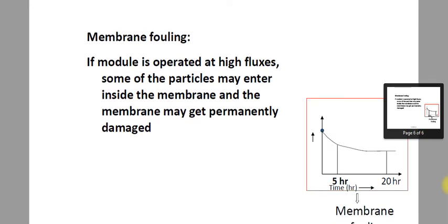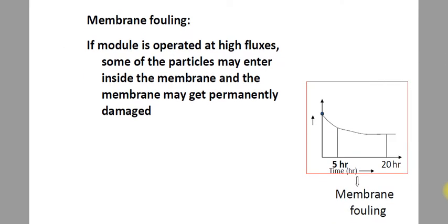Now there is one more technical factor which affects ultrafiltration, that is called membrane fouling. So what is membrane fouling? It is different from concentration polarization or gel formation. Because here you are separating out solid particles, there are chances that solid particles start to insert in the pores of the membrane, and it works on the pore flow model. So suppose the pores of the membrane are blocked due to the solid particles, then your flux will reduce with time. That is called fouling.